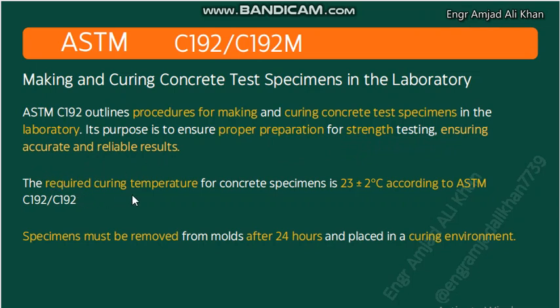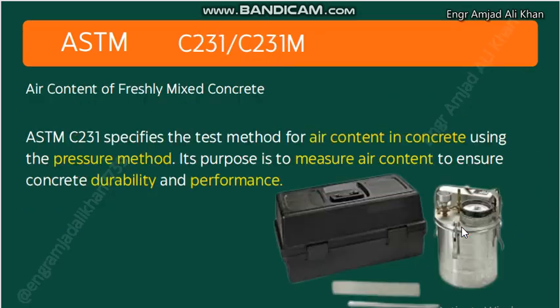The required curing temperature for concrete specimens is 23 plus or minus 2 degrees centigrade according to ASTM. This is, I think, 20 to 25 according to ASTM C192. Specimens must be removed from molds after 24 hours and placed in a curing environment, at the specified curing temperature.